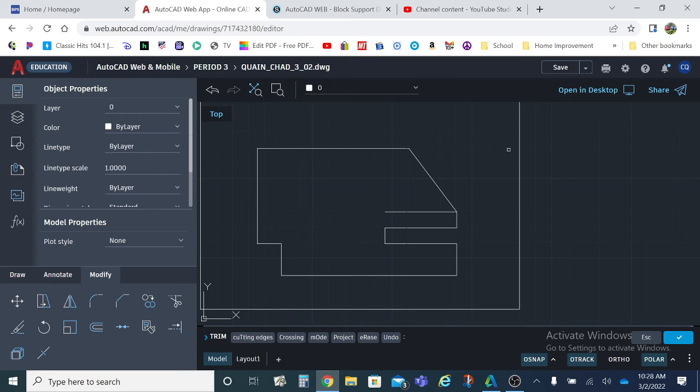As far as I am aware, in anything 2020 and older of AutoCAD on the client version, the one that would be on your computer, the desktop or the hard installed one, you cannot physically trim an object down to nothing. You're always left with a little stub of something. So in this case, trim allowed us to remove the whole object, but it did it in 3 steps, right?